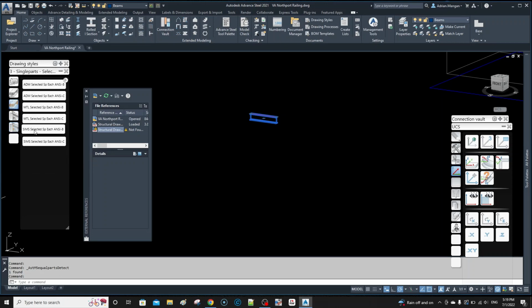It is not, because it should be in here, right? So I've created another one for assembly. Sorry, it's called test. So it's not available to me right there. So what I'm going to do is I need to shut these palettes down and exit Advanced Steel, and then come back in and open these palettes for it to be available here.